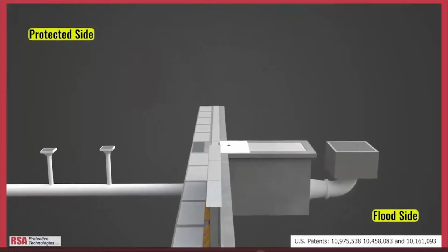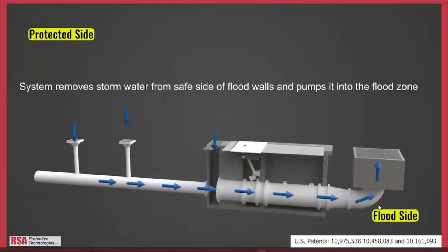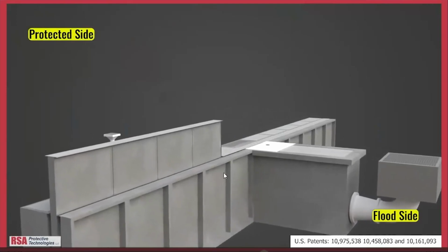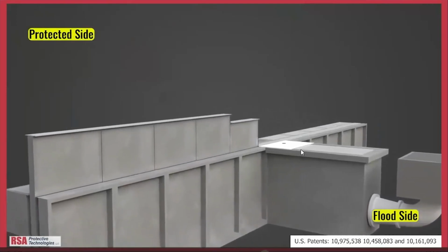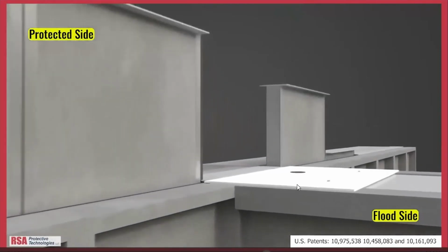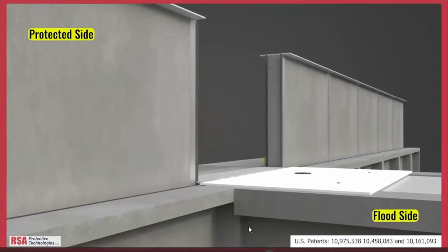Here's a little video showing how that works. This is the storm drain pipe showing here, and we have the monument around that, and then this would be the walls raising up on either side of that, and then a large steel ceiling plate, basically, that's either hydraulically or electrically operated, that would raise up and cover that opening where we couldn't have a retractable flood wall.